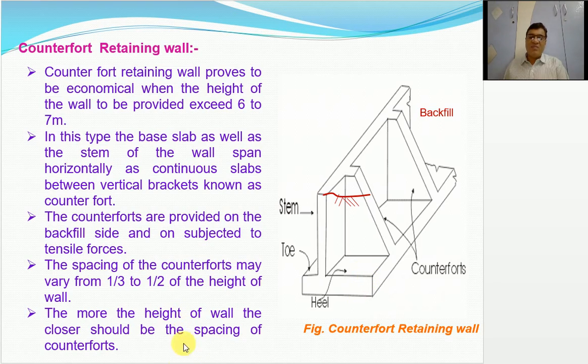Okay, let me show it here. Now this is the direction of the force for stem wall, and this is the direction of the force for the base slab. Now since both the forces are moving away from each other, the counterforts are subjected to tensile forces.